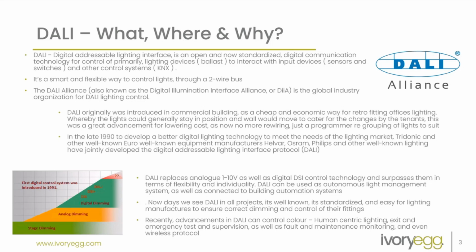The light fittings in the offices were set in their positions, and as customers or tenants would move in and out of the buildings, they would reconfigure the walls. Now, what Dali allowed us to do is, instead of wiring and putting lights into groups, we could do it theoretically through programming and make the changes just with a programmer and not have to rewire anything.